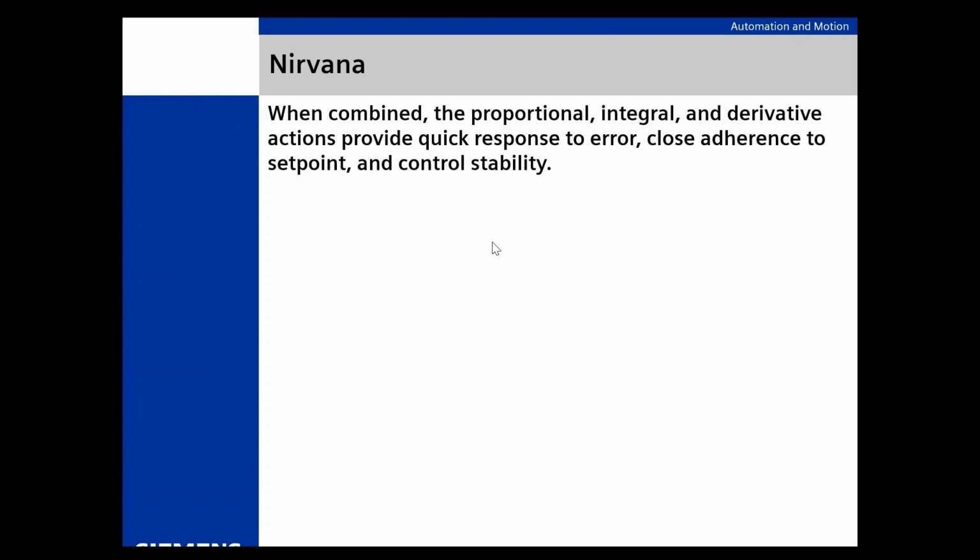Just one last one regarding the pH example. So that pH example, the derivative side of the PID really shines? Yes. Yes, pH is one of the hardest things to control. I do a lot of that, unfortunately. Here's the thing. The derivative is crucial.